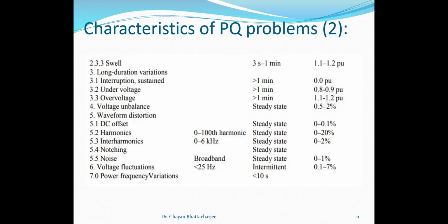As you know, say for a fully controlled full wave converter, in a 2-level converter, there are 3 legs and 6 switches. Then there are instances where a particular leg gets short circuited, and then there will be a voltage disturbance.